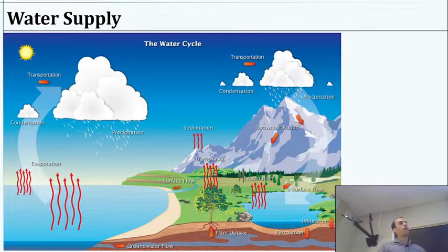If you go far enough, water can still transport, but on average, by the time water has transported 100 meters through soil material, there will still be bacteria and probably some viruses that feed on bacteria. But the ones that were human sourced and from some warm-blooded animal gut probably all have stuck to something by then. And now it's just natural soil bacteria and things that are still hanging out. Okay, so there's some benefit there. It's kind of a distance type of thing.